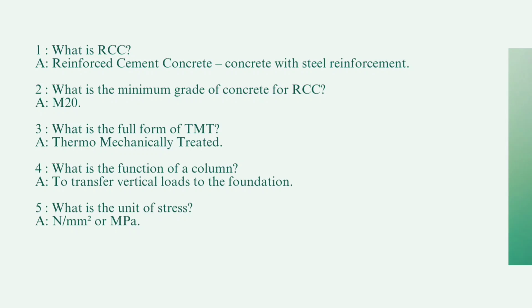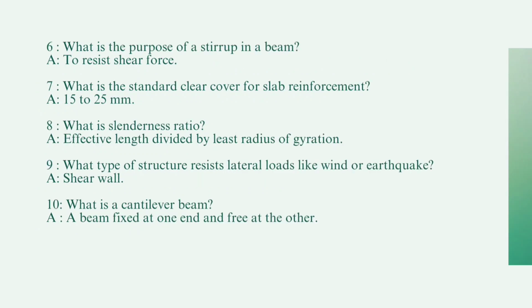Next question. What is the unit of stress? It is Newton per mm square or MPa. Question number 6. What is the purpose of stirrup in a beam? Answer. To resist the shear force. What is the standard clear cover for slab reinforcement? It is 15 to 25 mm.